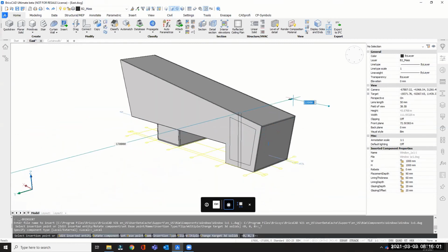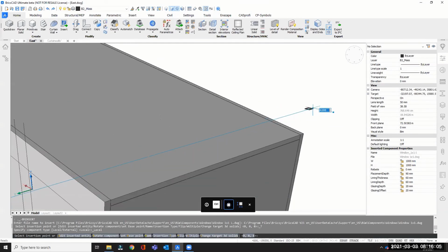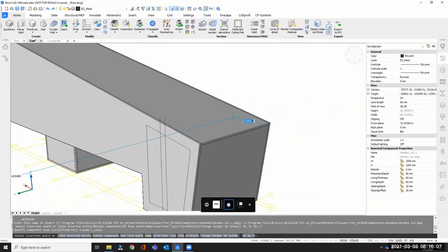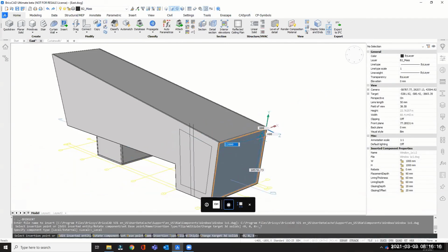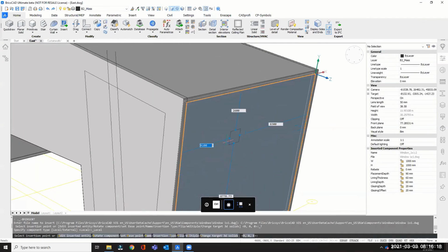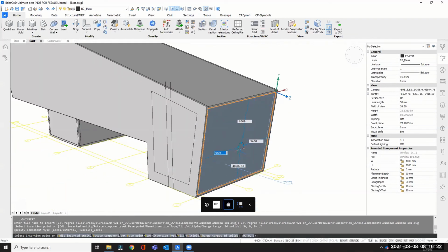It's just going to be floating around like that. So you see when I zoom in, it's there. But if I hover on my building, it's not going to be able to be inserted. So once I have my dynamic UCS on, if I click again on that, it will allow me to now insert this particular window into this part of my wall.